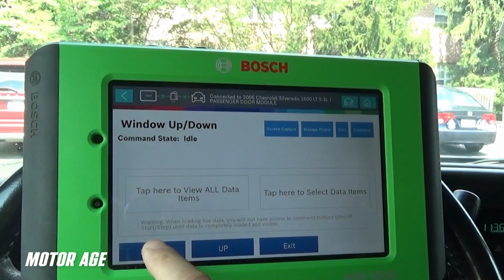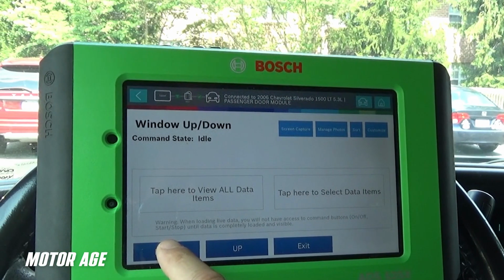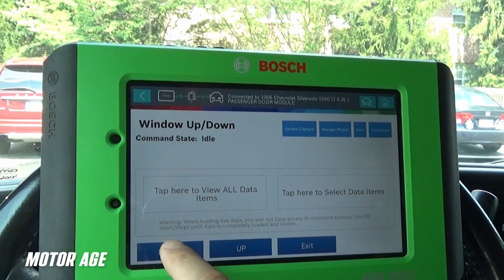Being able to capture a fault and prove where the fault may lie, try and triangulate its location through bidirectional control, allowing the scan tool to take control of PCM functionality and drive systems as a whole. And we've seen that in previous videos as well. But to then take control with that scan tool through bidirectional control, mode 8 of the scan tool, and actuate individual components, making them work, monitoring their functionality, perhaps with a lab scope and amp probe, or perhaps even just listen audibly for their function.